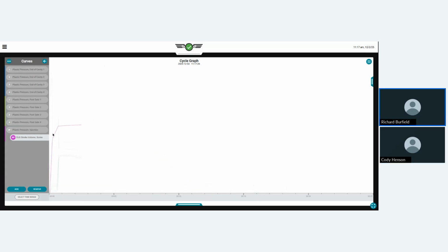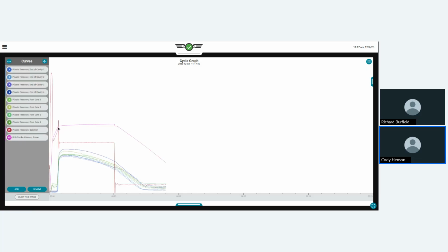returning to build its shot to return to that starting point. Yeah. And on that RJG stroke volume curve, that's why it's a must to set screw bottom, so it knows where our cushion is and everything. Yes, that's perfectly tied in. Having this scale correctly and be useful is critical to having that screw bottom set correctly.